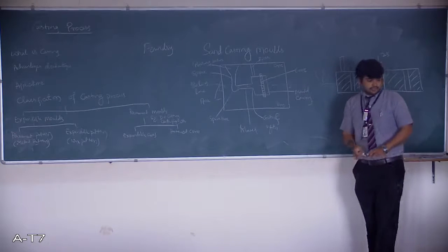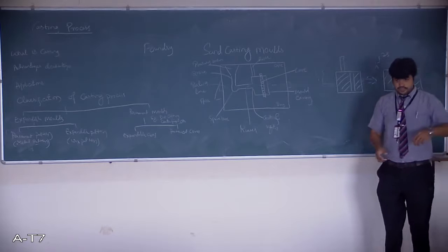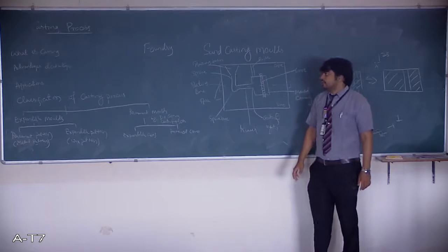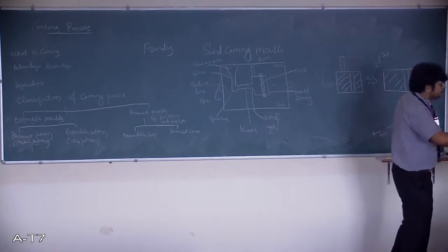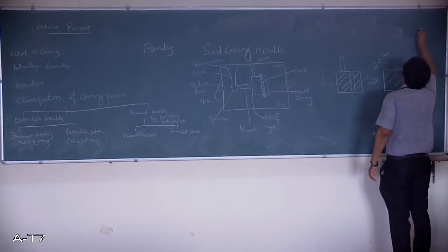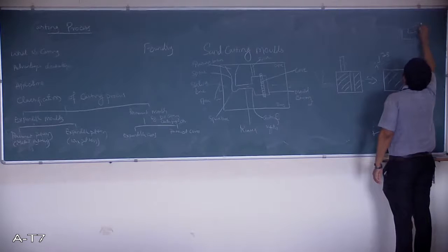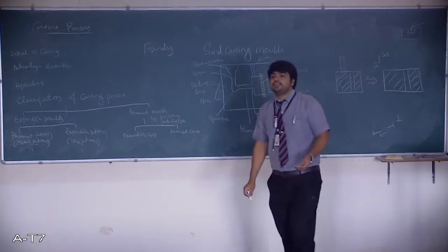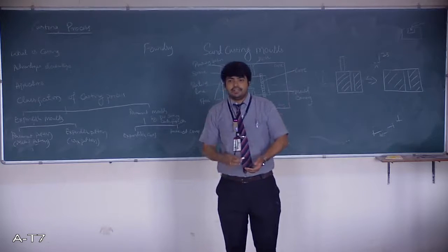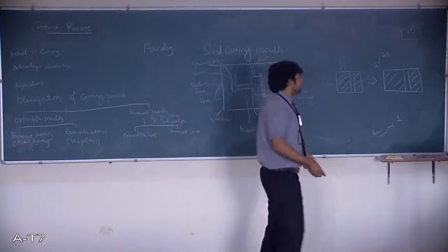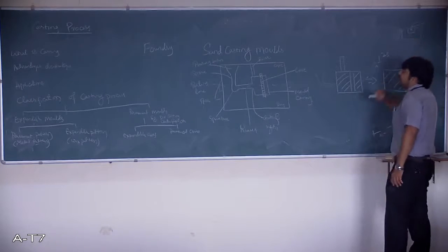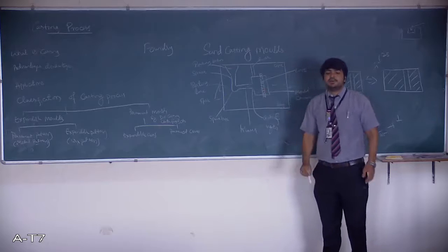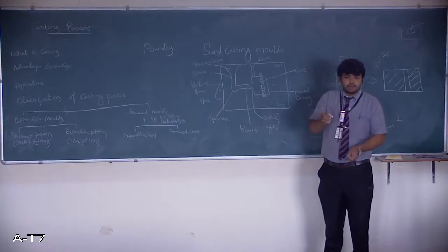So these are the elements of sand casting. This is the cross section of a typical sand mold. Instead of pouring the metal directly into the cavity, the metal has its own density and self weight, and with the help of acceleration due to gravity, when the metal falls, the mold cavity will get damaged. For that reason, we make use of these channels. The first part is the pouring basin. This part acts as a guide for the person who is going to pour the molten metal.